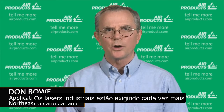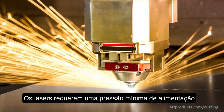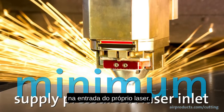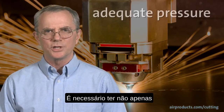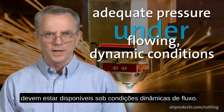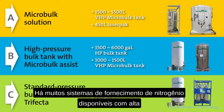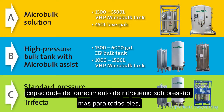Industrial lasers are requiring increasingly higher pressures and flow rates. The lasers require a minimum supply pressure at the inlet to the laser itself. It is necessary to have not only the adequate pressure, but it also must be available under flowing, dynamic conditions. There are many nitrogen supply systems available with high pressure nitrogen supply capability.